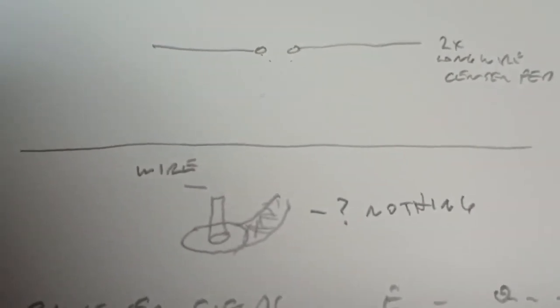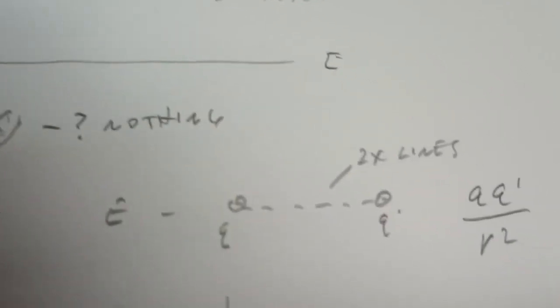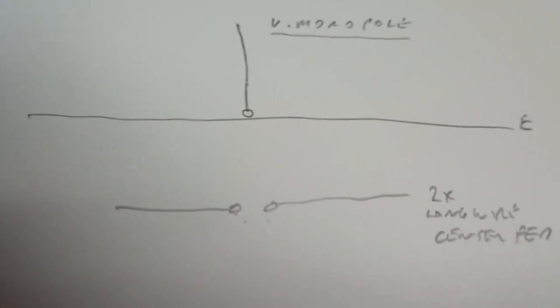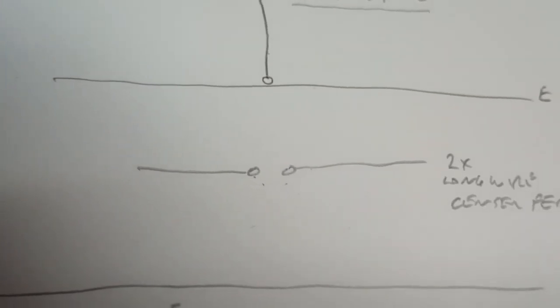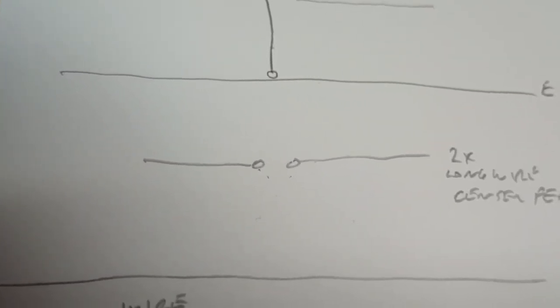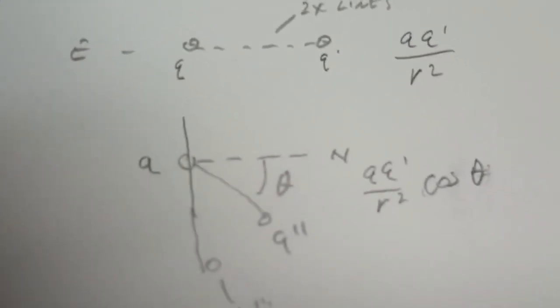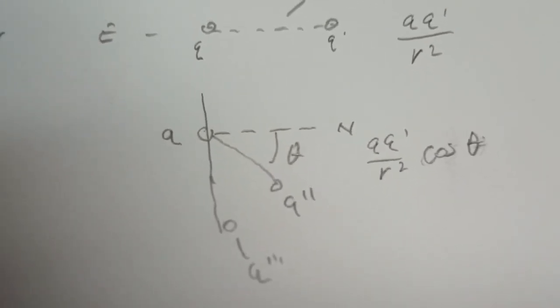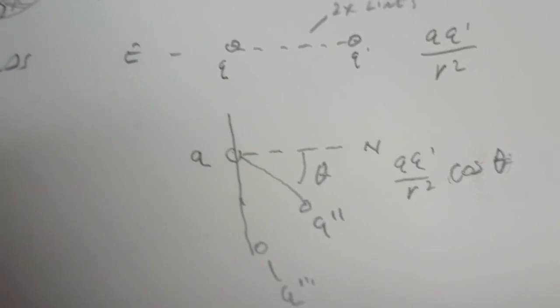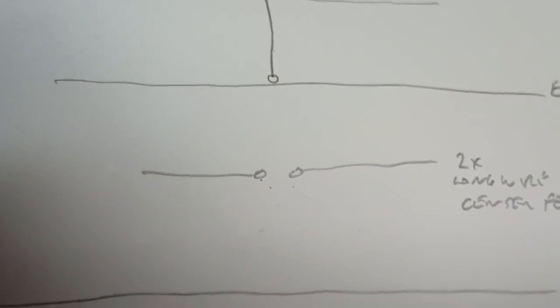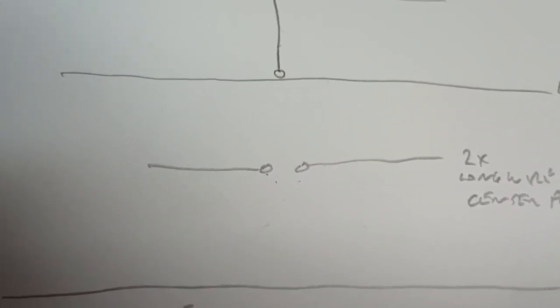So if we look at the shield as having charges, electrical charges, and it must, because it's essentially that system, charge pairs with field lines in between. What does that say about the dipole? Does it say that there is a field line concentration in between those two loops, which are the feed point? By this description here, with Q triple prime being essentially in line with the wire with Q and no field lines, what's that say about coupling from the feed point out along the wires? It says there ain't none. All the coupling is at the center.